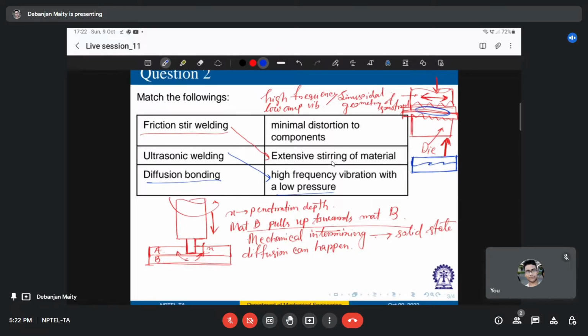So in solid state diffusion, the principle is the intermixing of atoms of two solid metallic surfaces between themselves over time, right? So diffusion is aided by what? Some intermediate heat, maybe 50 or 70% of the melting temperature, along with high pressure for a period of time. This period of time can be 1 hour, 2 hours, 3 hours, depending on the material combination. And when the asperities on the two surfaces contact and plastically deform, they interlink, forming interfaces between the two surfaces, right?